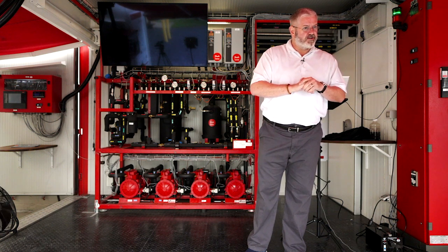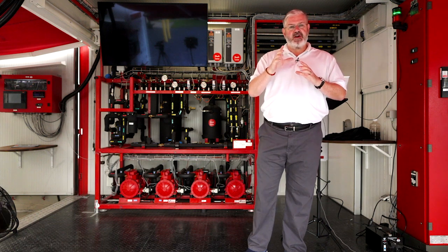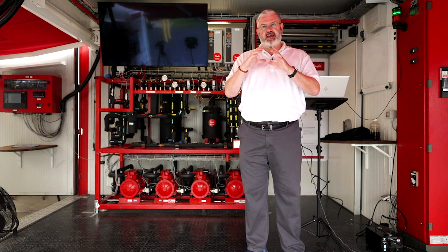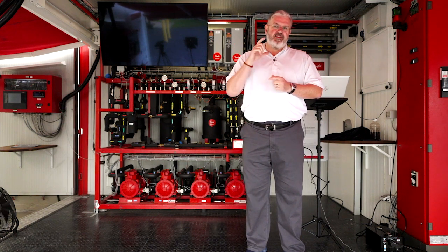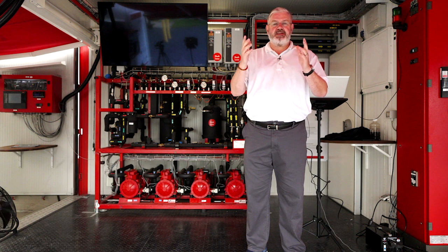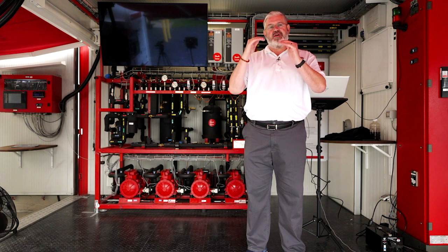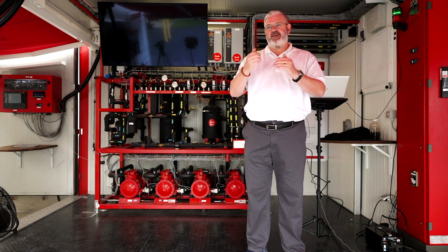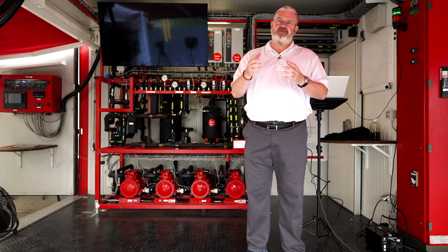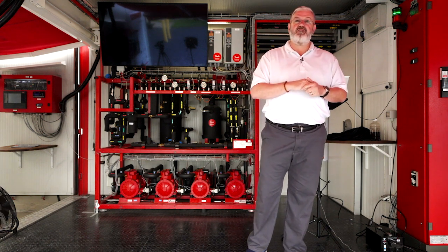Excuse me, how does the controller determine capacity required from ejectors? So it's basically defined. That's a great question. I had never had anyone ask that. So it's defined within the controller, not unlike condenser fan banks. You select a model for the ejector. So I think the one on the table over here is an HP high pressure 1875. When you select that model, it knows what ejectors go in that, and it'll predefine the various capacities of the ejector blocks based on the model entered in the software. So in theory, you could have some control issues with an ejector block. Might want to check the model on the ejector block itself and verify that's what's defined in the pack controller.